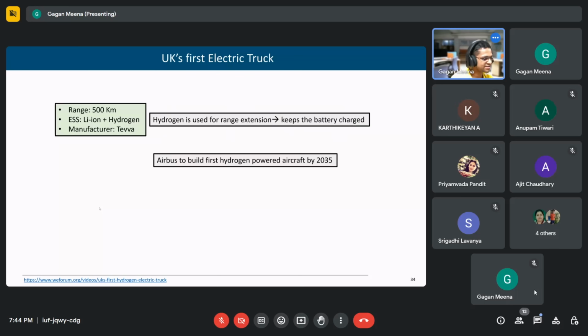That is why the government has started this National Green Hydrogen Mission, so that we have the capacity to produce green hydrogen. In the last to last session, someone was asking about multi-vector systems. So this is an example of a multi-vector system. Here hydrogen will require electricity for electrolysis, for production of hydrogen, and then it will also produce electricity. That electricity it will take either from the grid or from its own plant. So now we want to plan for both hydrogen and electricity; the electricity network and hydrogen network have to be planned together.